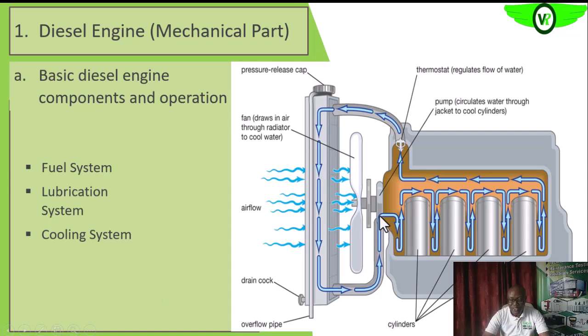Okay, we have a cooling water pump, which is the first part of the cooling system. This is the cooling water pump. Okay, so then we have a reservoir of water, and then the cooling water pump sucks in that water and sends it into the engine. You see the part circulates around those cylinders, to remove those excessive heat from around the cylinders. So in the block we saw earlier, you saw those holes. We'll see it later again. Those are the holes for water to go through. Even on the cylinder head itself, there are channels through which the water can pass. So, but summarily, this is what it does: send the water pressurized at a particular pressure into the engine to carry off the heat. Okay, then it is sent back into the reservoir.